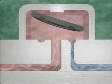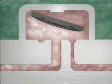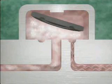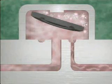During normal operation, hot condensate entering the trap experiences an increase in velocity and a reduction in pressure. As a result, some of the liquid condensate changes state, flashing to steam. Because steam has a greater volume than an equivalent weight of condensate, the velocity of the flow through the trap greatly increases after the flash steam has been generated. This further increase in velocity reduces pressure on the underside of the disc.